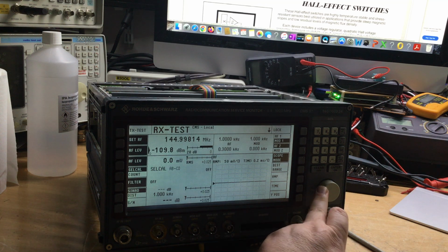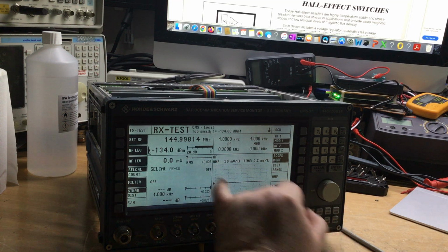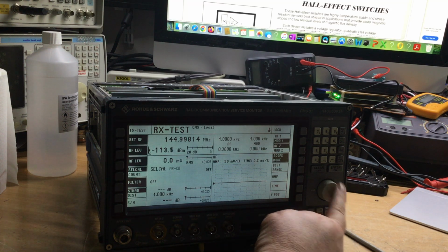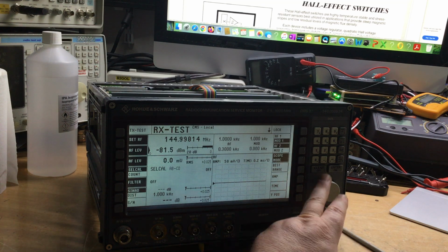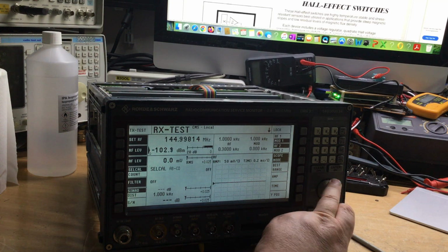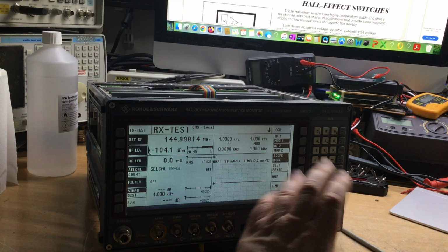Before then the other fault developed, which is where it just started going down to the minimum level, which is about neg 131, neg 134 dBm there, and then likewise it would carry on going up the scale to the maximum RF level that it could put out, and thus obviously say the same thing to higher level. But as you can see there, quite nice control of the output level without any issues up or down. So I believe that's repaired it.